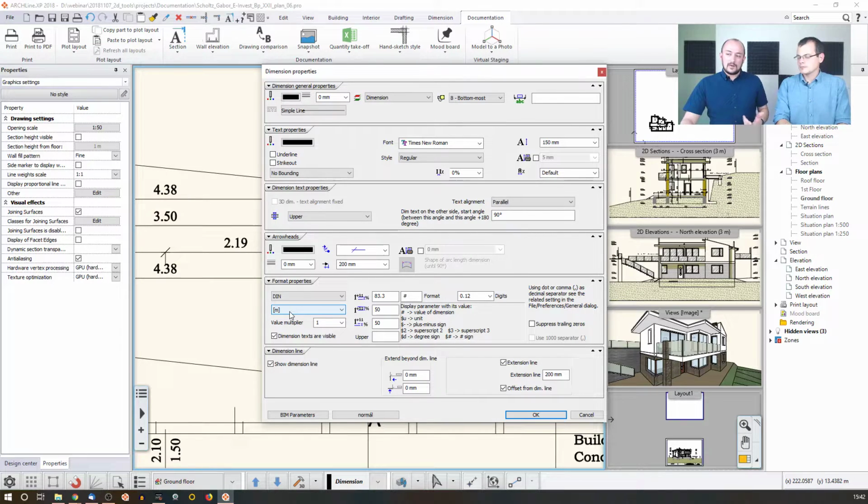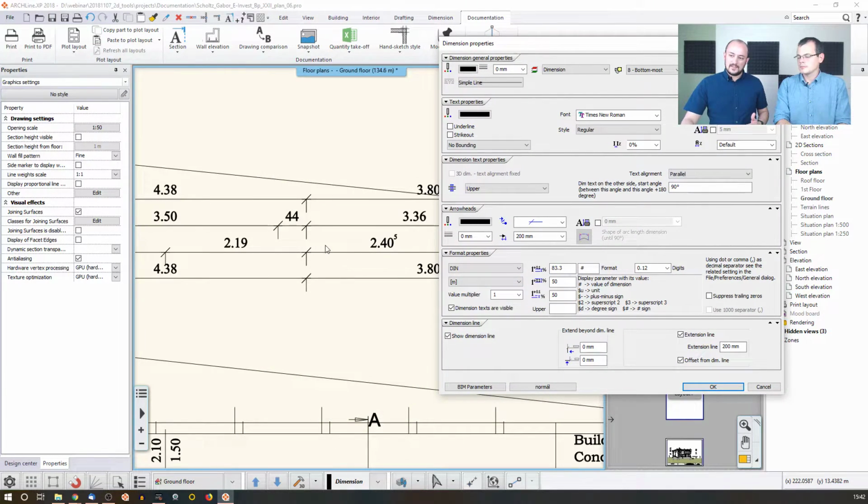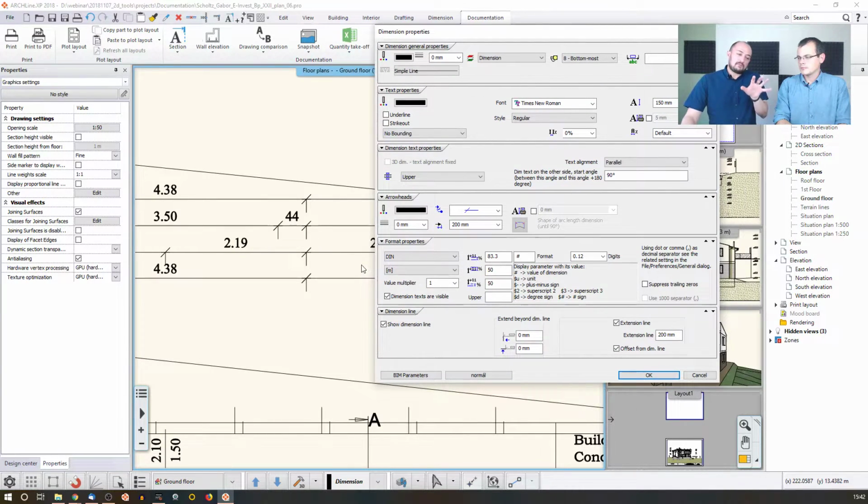And the way I'm about to measure the content that I have designed, because don't forget, this is not really the documentation. This is the building itself that you recreate virtually, and then you measure it. And then you can decide whether that specific thing, which is having a specific size, is measured in meters, in millimeters, in inches, in feet, and so you can make changes here. For example, I'm working with a carpenter, and my carpenter needs sizes in centimeters. So I just click here and say, okay, this is DIN in centimeters.